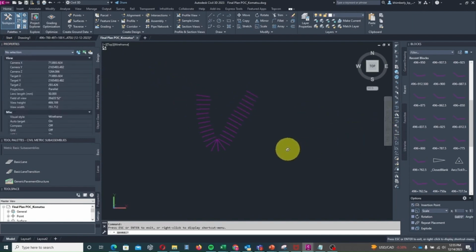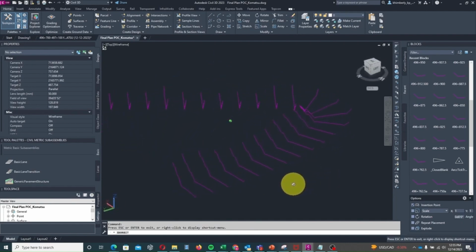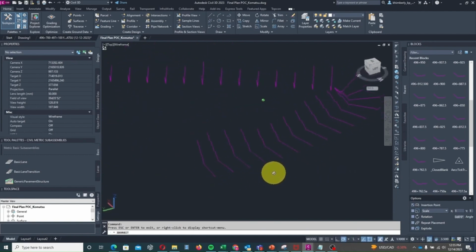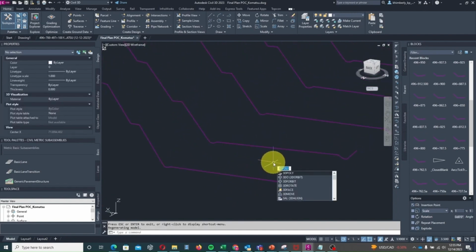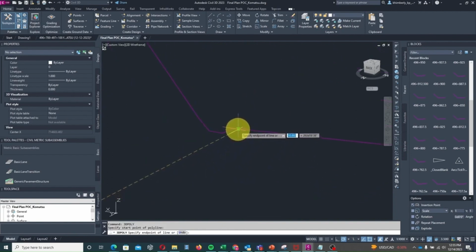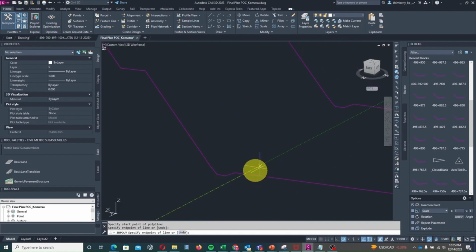Next step is to connect the vertices of the cross-sections. To do that, rotate the drawing as shown. Use 3D Poly command. Then, draw 3D polylines connecting the vertices of the cross-section as shown. Proceed to 4 minutes 35 seconds of this video to see the completed drawing.